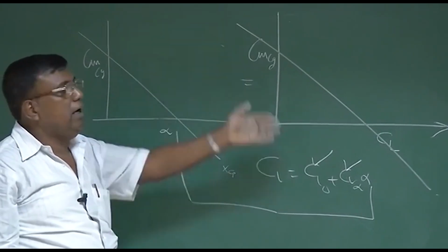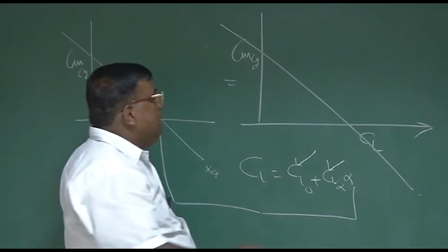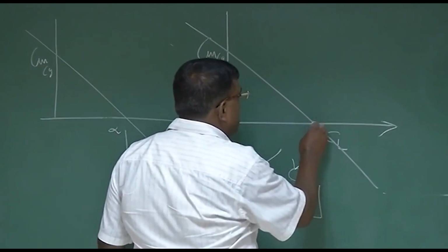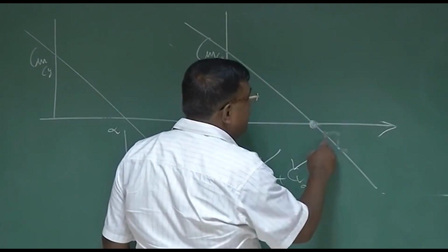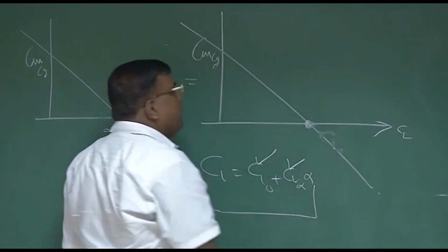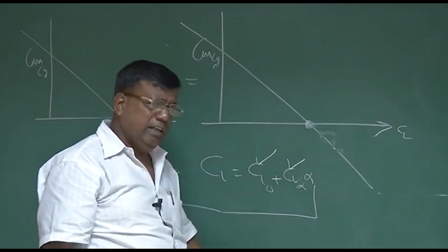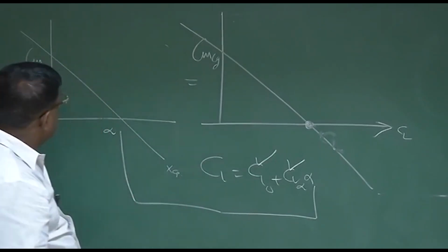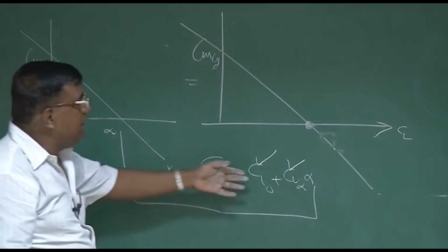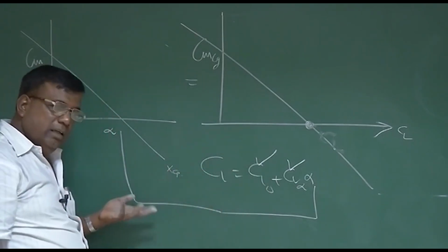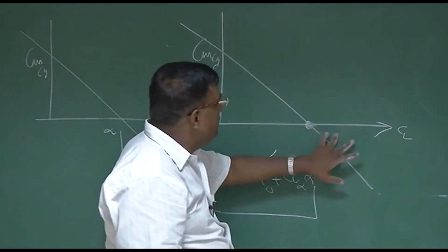Now let us check the trim point, the equilibrium point, whether this aircraft is statically stable or not. We know the CM versus alpha slope is negative, and because alpha and CL are related like this, the slope has to be negative. But let us add some physics to it.